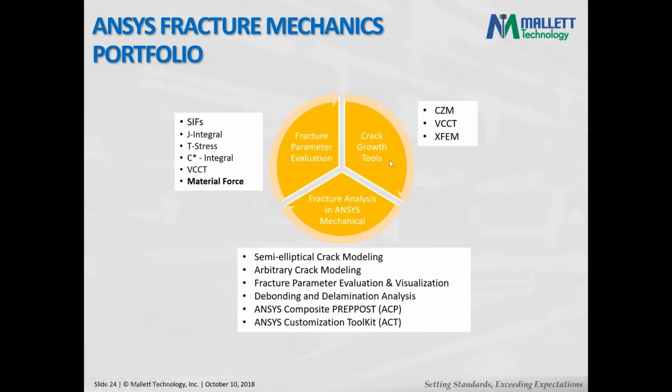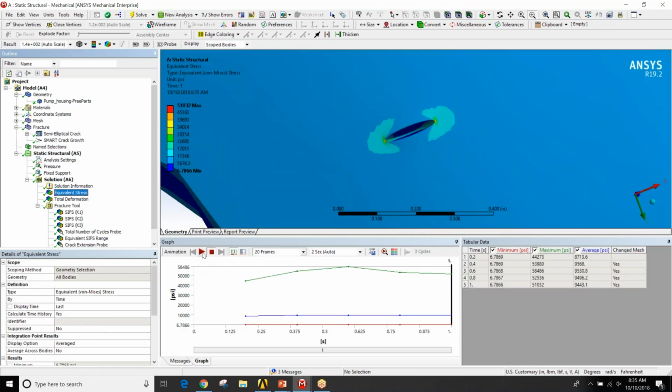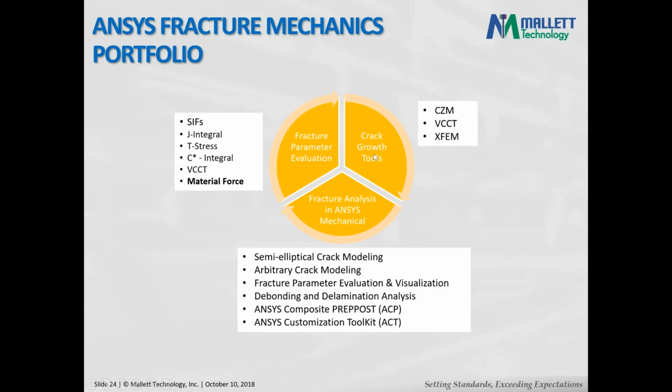And also crack growth tools. How can we do crack growth simulations? As you see here in ANSYS, yes, we can do crack growth simulations, just like what we are seeing here. For the crack growth tools, there's the CZM method, there's the VCCT method, and the XFEM method. Those are all available.